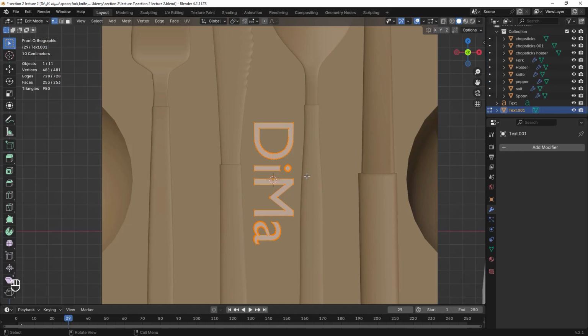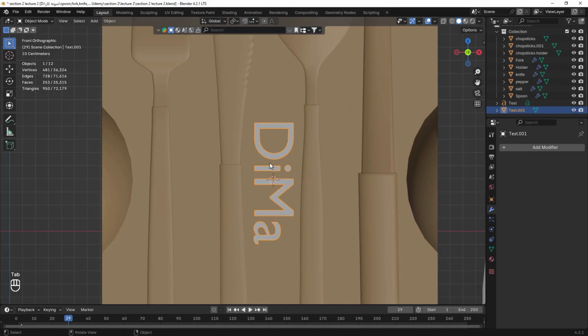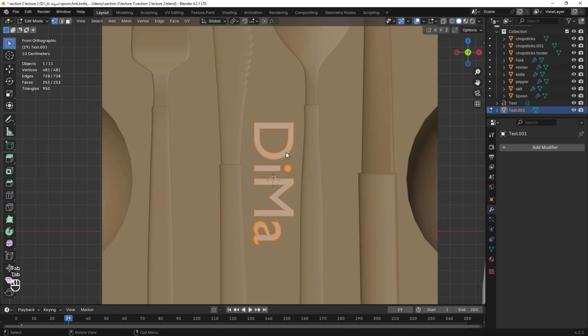253 faces to be corrected. As you can see, we have better meshes in the edit mode section, and by pressing the M key we activate merge and select the distance option.